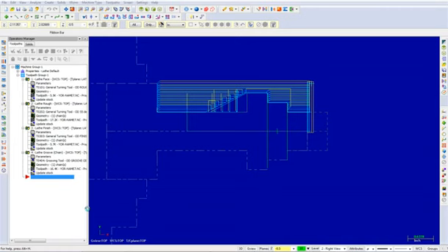In this video, I will demonstrate and explain the parameters used to create a C-axis face contour toolpath. C-axis face contour creates a toolpath on the face of the part with the tool parallel to the axis of rotation. Left-click on Level in the status bar.